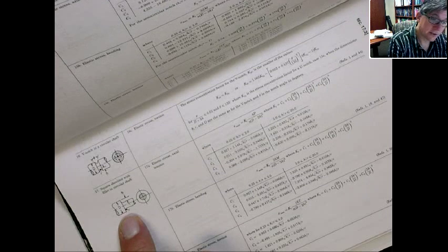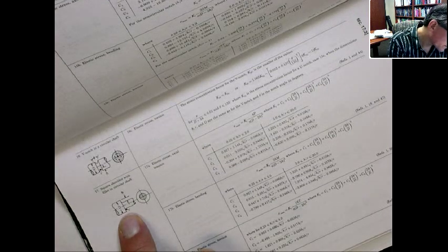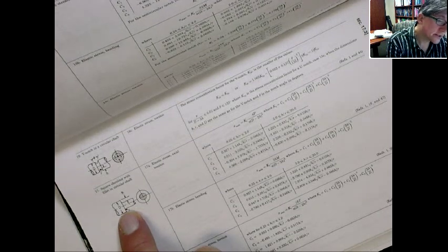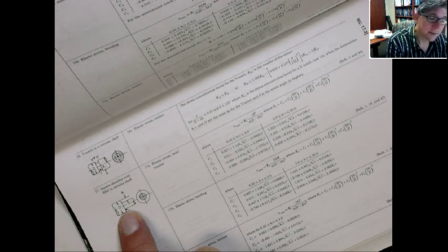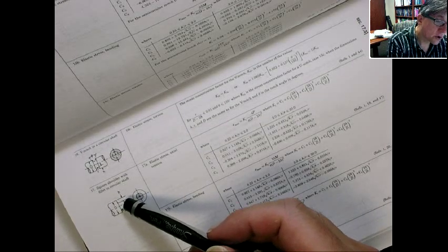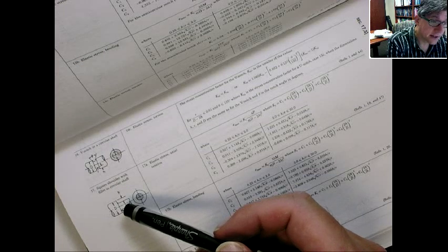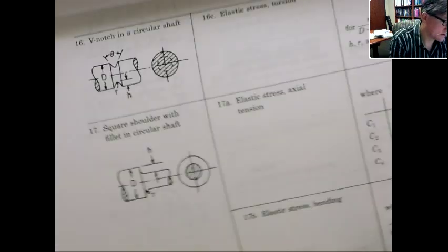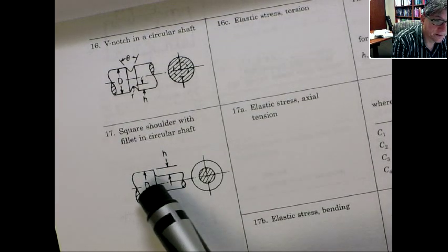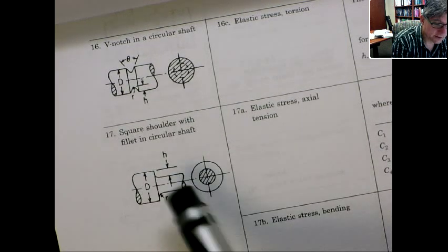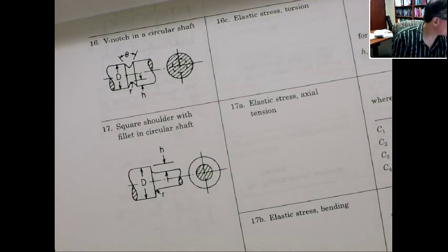A circular shaft. This is a torsion one, I believe, right? Yeah, this is actually torsion, but it's the stress concentration factor you get here for torsion. So it goes the same way, although I don't know if we'll cover explicitly stress concentration factors for torsion, but you do it in the same way. You could figure out on this smaller area the torsional stress, the TC over J, and then right at this fillet, let's zoom in just a little bit, you'll get a little amplification of the stress, K.